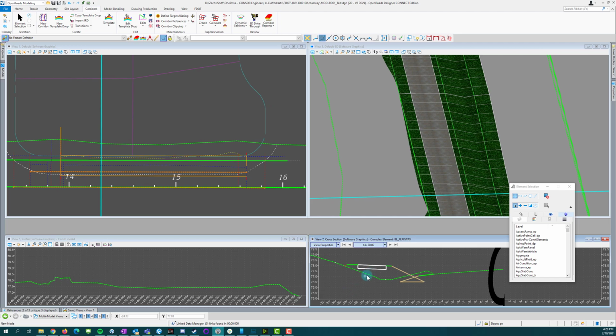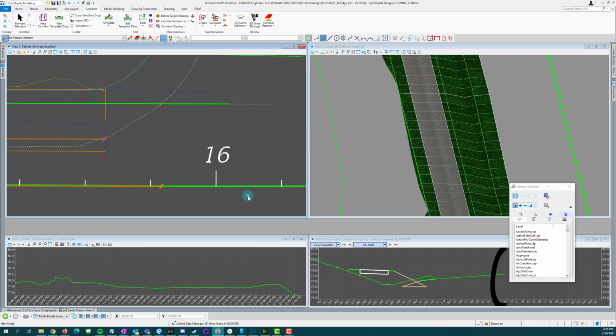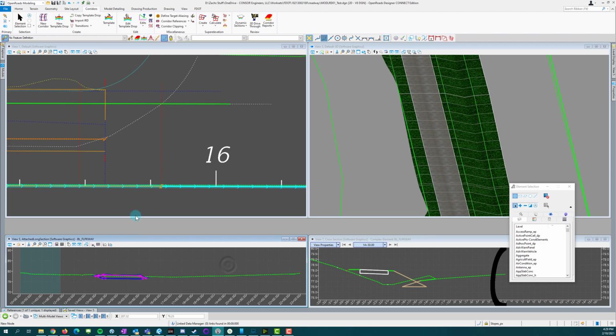It looks to me like in this middle area, we really have to drop this sidewalk down quite a bit more. So that's what I'll try and do real quick, is basically I need to add another point in there. Let's see what this looks like. So the good thing about ORD is you can actually look at your profile while you're in another file. Yeah, so we know we need to get up to this driveway, and then it looks like maybe we need another point that's here to try and get this down as much as we can. Because we're pretty much set on where this ditch has to be. We're set on where our edge pavement is. So this sidewalk has to come down quite a bit.